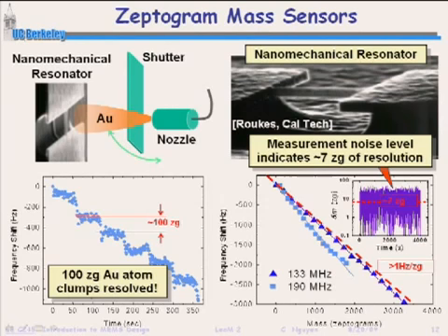So this is detecting about 100 zeptograms of mass change. What's a zeptogram? That's the question that comes in, right? With this going to nanoscale, shrinking things down, we're now dealing with words we don't really know that well. Zepto is 10 to the minus 21. So we're detecting extremely small masses, and we're getting closer to being able to detect single atoms with this type of technique. And this is all a resonant sensor. It's become much better just because you've shrunk it down enormously.